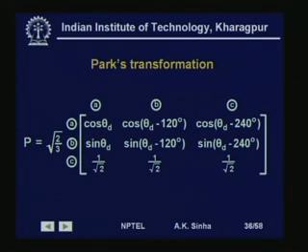Since that has nothing much to do, we generally do not use that part, but we have the D axis, which we call the direct axis, which is in phase with the rotor, a quadrature axis which is at 90 degrees to the rotor, and the third one, a 0 axis. So, the dq0 frame of reference.